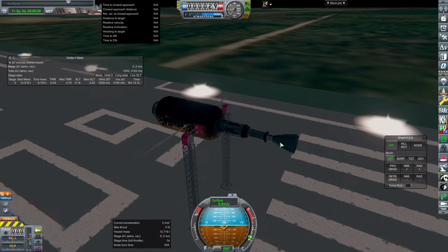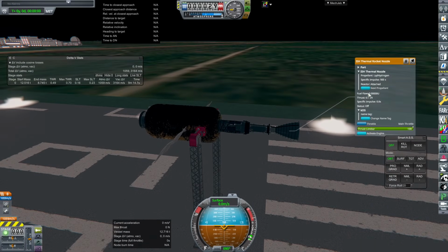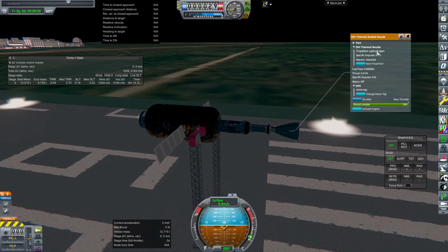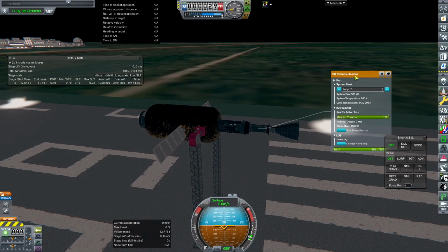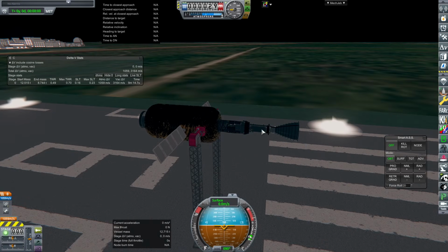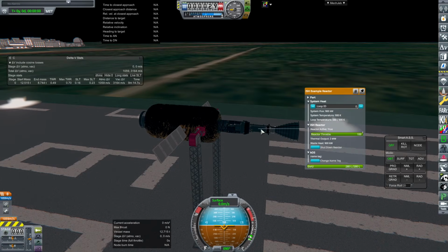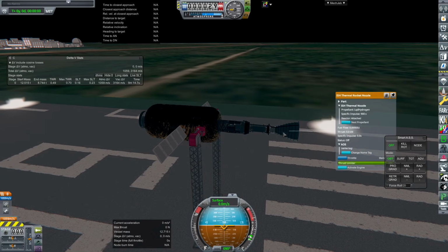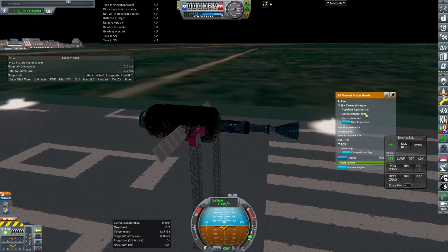Out here, we can change the attached propellant, by the way. There's no methane here, it's just hydrogen. I've only got hydrogen and methane as choices for now, but it's a configuration file that has the list of propellants. There's also a configuration file for the list of different types of reactors, so we can have a liquid core or a gas core or something like that. That will produce a different specific impulse, so the specific impulse is dependent on the propellant and the type of reactor.